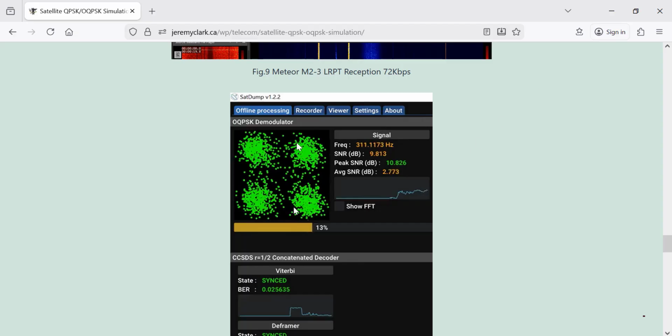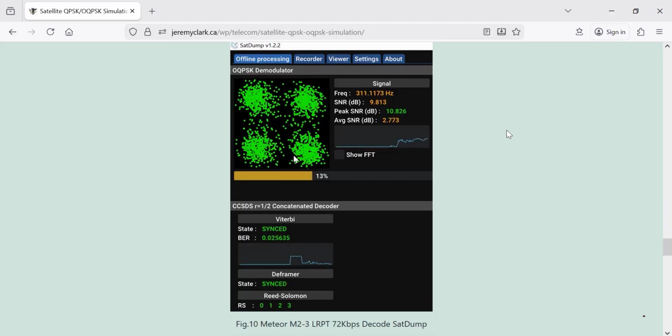You get the 4 points here in the constellation diagram. Historically, QPSK is quite interesting. Way back when I started my career in the 70s, Canada was converting its analog microwave to digital, and they started off with a very neat idea, and they put in a subcarrier above the analog baseband. They put in a 1.544 megabit or T1 signal using QPSK. It was called data above voice. This was a system that was pioneered by Dr. Camilo Fairhair. So QPSK has a long history. It's well understood, and it's a very robust modulation scheme.